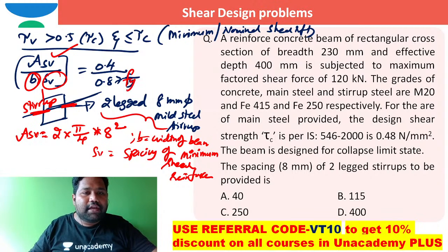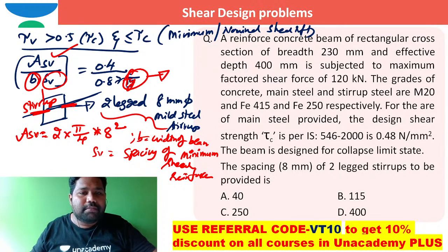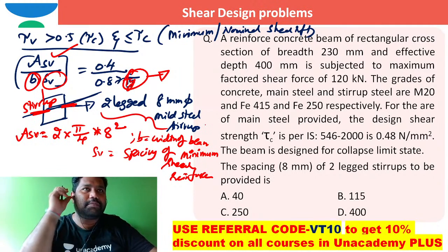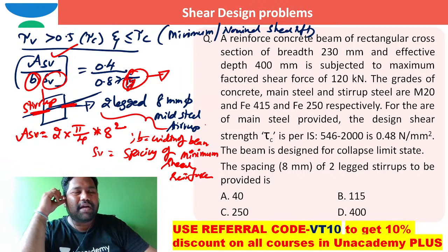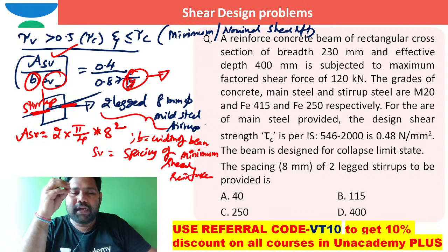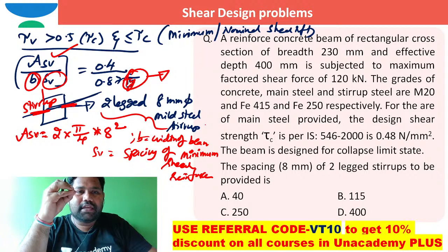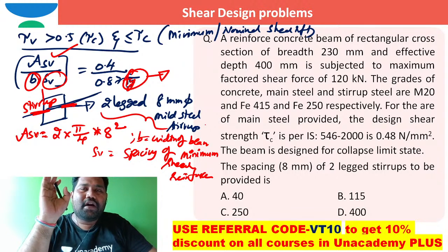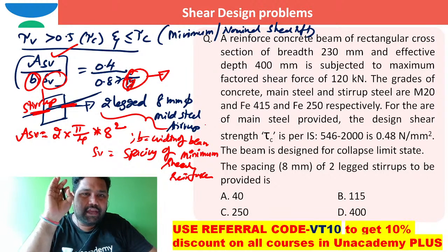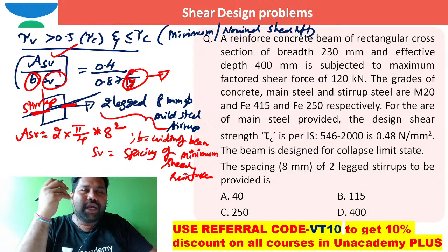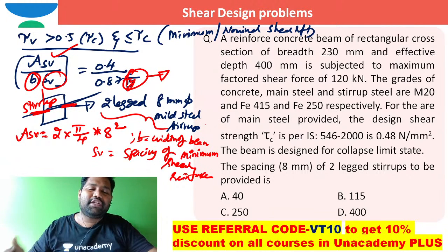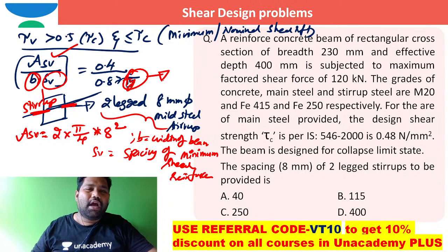Now here fy stands for the yield strength of shear reinforcement. Out of HYSD bars and mild steel reinforcement, mild steel reinforcement is good for shear reinforcement because it provides more ductility. To achieve more ductility for shear reinforcement, we need to provide mild steel stirrups. So generally, if nothing was given, we do the design with mild steel stirrups. So maybe fy I can write as 250.